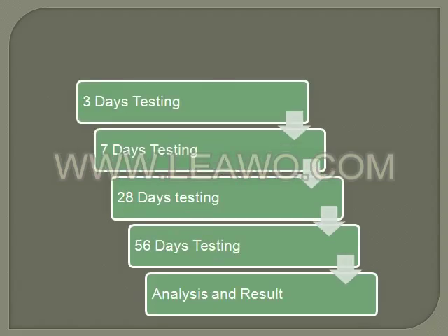After casting, we carried out 3 days testing and then 7 days testing, followed by 28 days testing, and then finally 56 days testing. Then we analyzed the results and then we concluded with the best performing concrete.